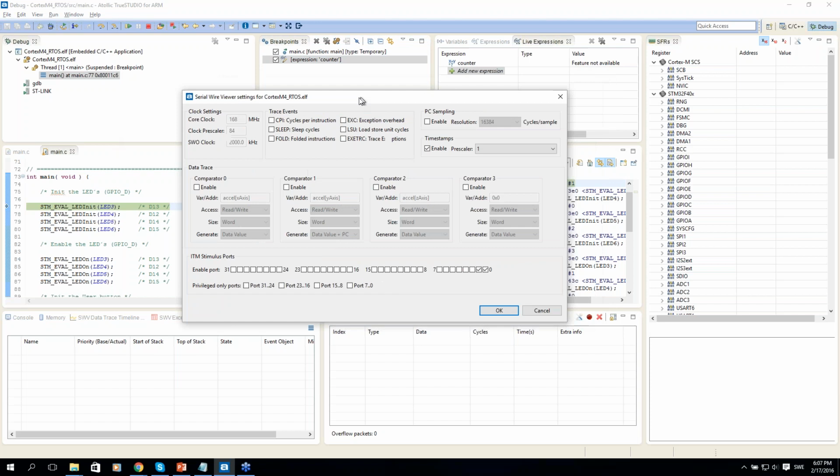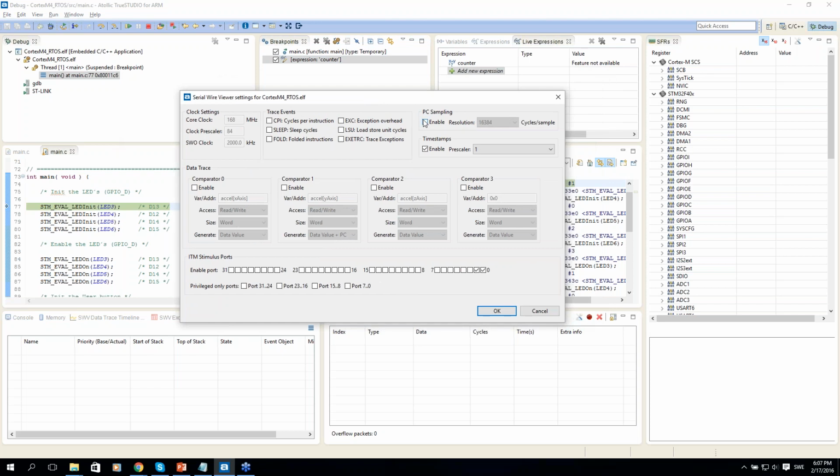I can configure the trace to output trace data for each program. We can sample a program counter, and each sample generates a trace data packet back into the debugger. And by doing that, we can enable statistical function profiling. Also, we can have the target generate trace packets as soon as an exception or interrupt occurs in the target. So that's another type of event that can generate trace packets. And here is where I control which types of events will generate trace data.